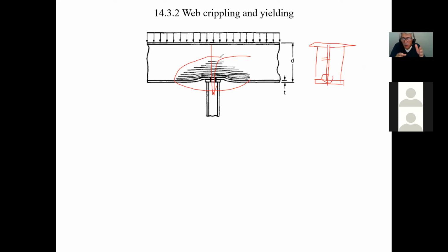Now, I can tell you right now, guys, 99% of the people in the industry, they don't even bother calculating this. They just put the stiffeners right away. They figure whether we need them or not, I'm not going to break my head, I'm just going to put them in, and this way I know it's stiffened. So that's what they do. And I consider that to be bad practice. I mean, it's a waste of material and a waste of time.